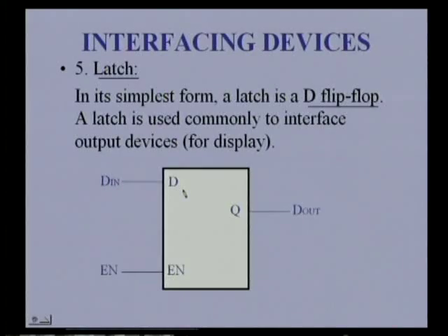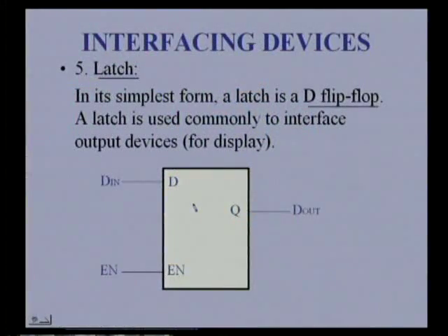You know the job of this latch, as we were discussing earlier: when the lower order address data multiplexed bus is demultiplexed, we have to copy the address into latches. That is done by using an octal latch, which has 8 latches similar to this as shown in this diagram.